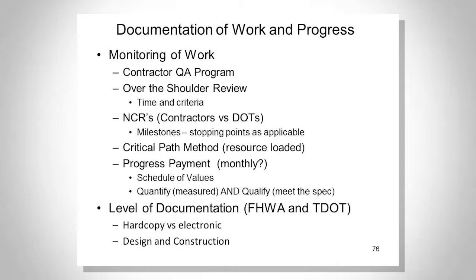Talking about progress payments, like I think John mentioned a little bit earlier, talking about quantity we want to measure, and quality, make sure we meet the spec. If you're going to pay for it, do some spot checking to make sure that it's actually meeting the spec you're paying for. And again, with the NCRs, you may want to make a point that if it's an NCR, you don't pay for it, or a portion of it, not the whole thing, till it gets corrected with the appropriate credit and or mitigation as applicable.